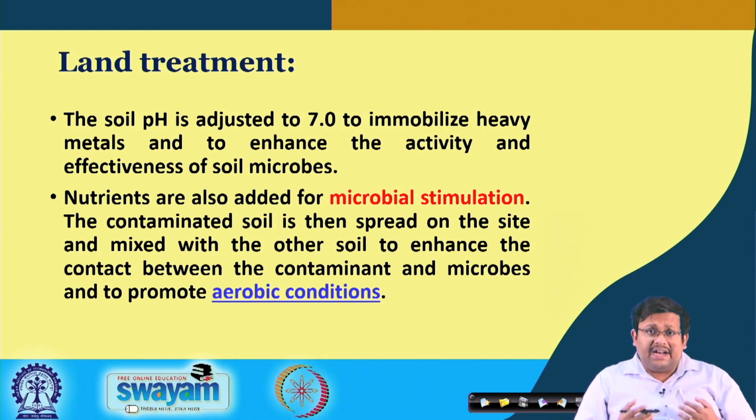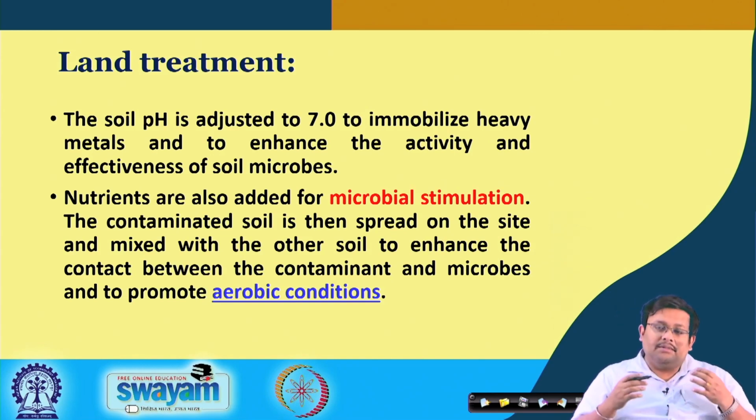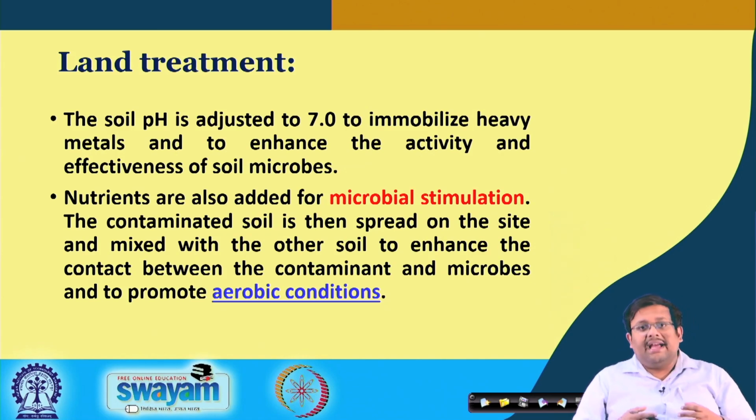So, sometimes we also add nutrients for microbial stimulation, because when you apply the nutrients, that will help in microbial growth and then stimulates the microbial growth for further degradation process. So, the contaminated soil is then sprayed on the site and mixed with other soil to enhance the contact between the contaminant and the microbes and to promote aerobic conditions. So, the aerobic condition is needed for most of the microbes which are aerobic in nature, and by the stimulation process their activity is enhanced, and ultimately this enhanced microbial activity degrades the organic as well as inorganic contaminants.